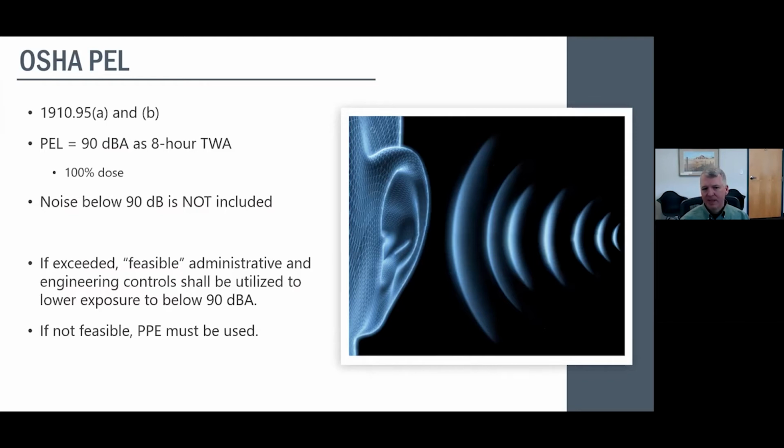But they basically say, in their field operations manual, that once a time-weighted average exposure is above 100 dBA, hearing protection really is not going to be enough to lower that exposure to below 100. We're not really going to get into noise reduction ratings and all that, or we'd probably be on here for a couple of hours. But basically, OSHA's really not going to cite you for that.